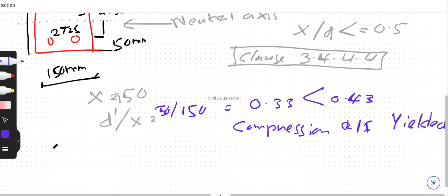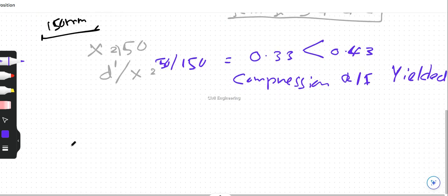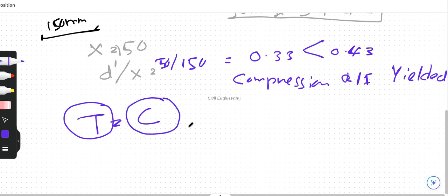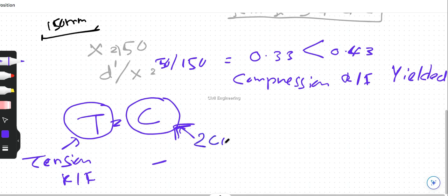So as the forces inside the beam are balanced, or at the equilibrium stage, we can take that tensile forces are equal to the compression forces. Here tensile forces are carried by the tension reinforcement, while compression is carried by two components.